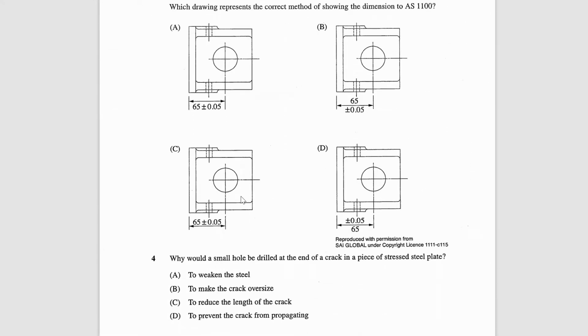So there are some drawing standards that we need to learn about, things like tolerances. Tolerances: sometimes we're going to say that we don't know the dimension, or we can never manufacture something that's perfectly 95 millimeters. It could only ever be 95.000000001 millimeters, right? Eventually we're getting to the level of atoms where we can never get perfectly to this platonic ideal of 95 millimeters. So what we're saying is it's 95 millimeters, give or take 0.05 of a millimeter, right?